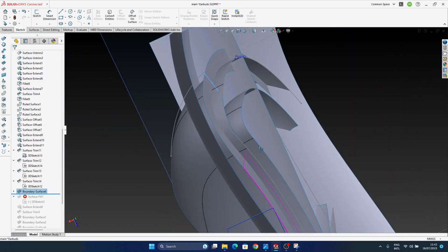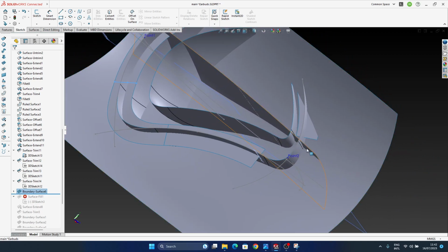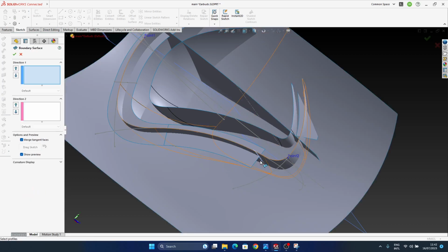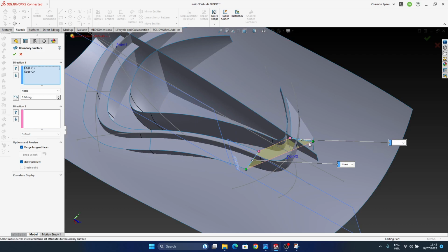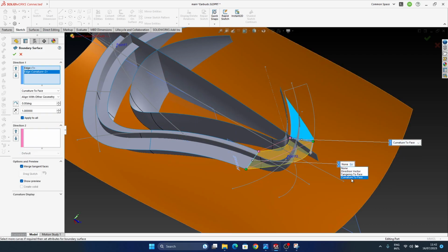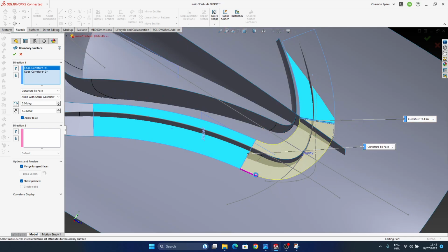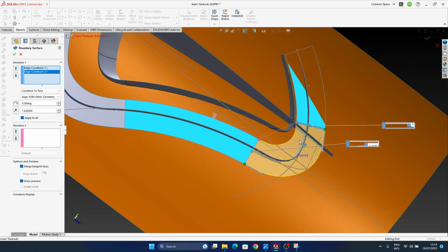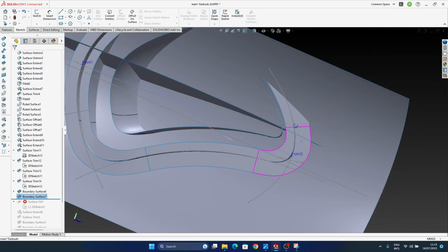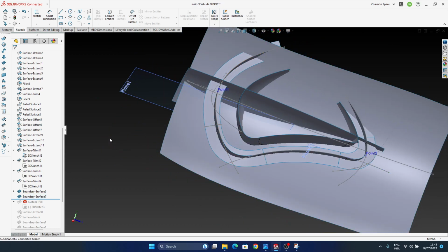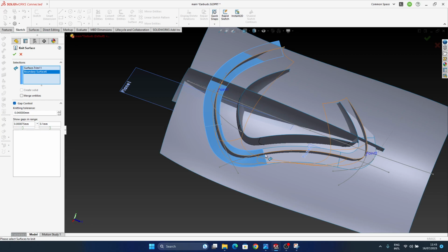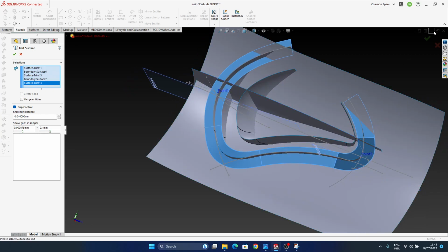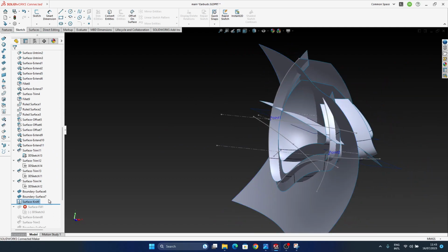So these surfaces are not too big, so at some point we may end up having some issues with them if we modify the model way too much, but it's going to work far better than having those sketches and curves. Yeah, I didn't expect SolidWorks to be so sensitive to vertices, but yeah, it is how it is. Again, at the end of the day, it's quite cheap as a software. All right, so we can give up on that surface fill, which doesn't work.